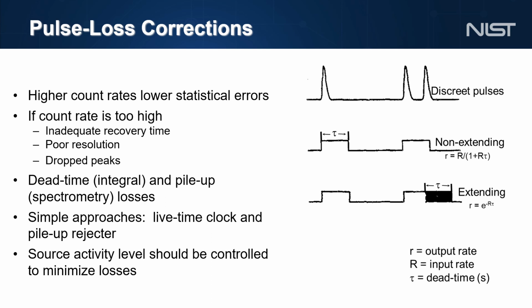Dead time, the downtime for signal collection and processing, which is specified for the instrument, can result in a lost peak. Correction of results for counts lost during the analyzer dead time can be overcome by carrying out all counting runs for known or measured total instrument lifetimes, rather than for real time, which remains valid even if the dead time varies widely from pulse to pulse.